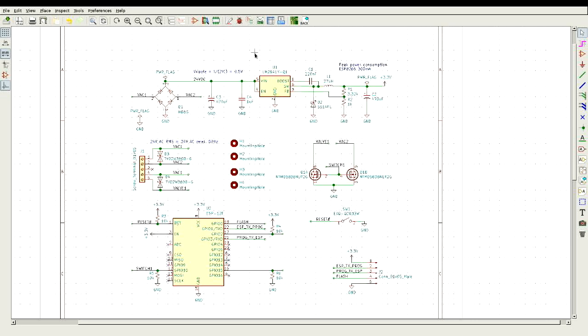If you hold down the delete button and then select, it will actually delete everything that it touches. And the only other, I have to press Z. The only other tip is often copying using C is faster than adding a new component pressing A, just to make life a little easier.